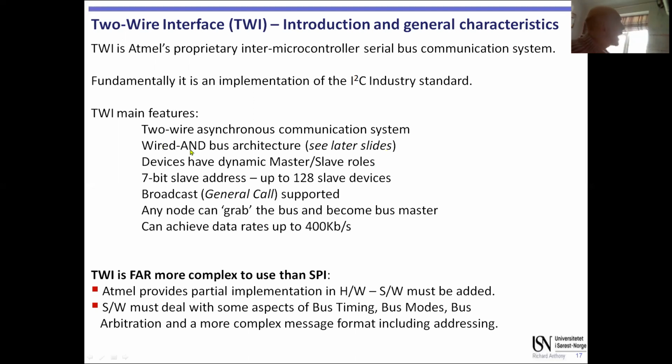But wired AND means that if one device is transmitting a 0 and one device is transmitting a 1 at the same time, the 0 will win, okay, because it's been pulled low with more power, if you like, than the 1 has. I'll explain that with a diagram.